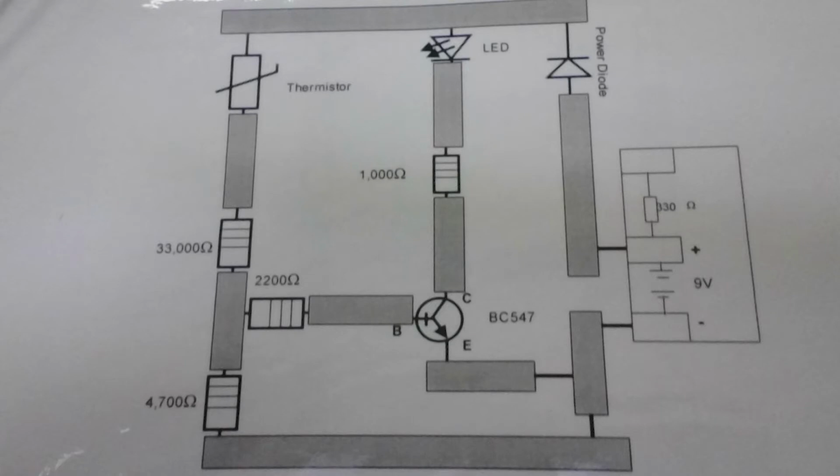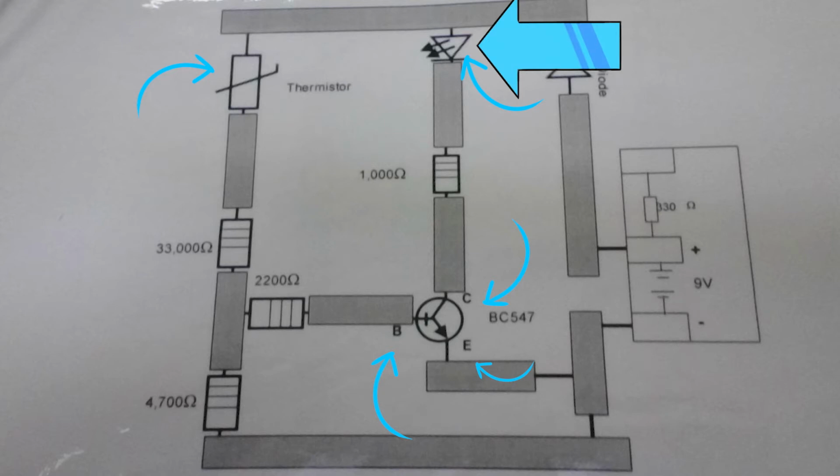Let's look at how this thing works now. Starting from the battery, the electrons move to 2 places. They can go through the LED and get stopped by the transistor, or they can go to the thermistor. When the temperature is low, the thermistor has a very high resistance and blocks the current from passing, and the circuit is broken. However, as the temperature increases, the thermistor eases the resistance and the electrons flow through. Let's ignore the bottom part for now and we'll assume all the current flows right. The current goes to the transistor and the transistor opens and allows the cut-off electricity to flow down. The new circuit is now closed, and to alert everyone of the urgent situation of a fire, a little light turns on.